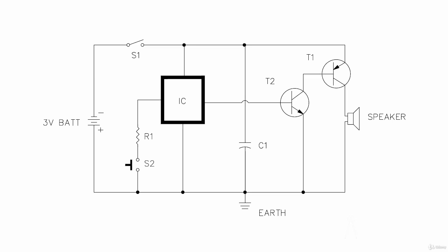In this video, we'll make an entirely different kind of drawing, and here we'll make a circuit diagram of a simple doorbell. So we'll use a lot of different blocks like the transistors, NPN, PNP transistors, speaker, IC, resistors, switches, battery, and so on will be needed. So we will not make all of those symbols. Instead, we'll use all the ready-made symbols which are available in the design center of AutoCAD.